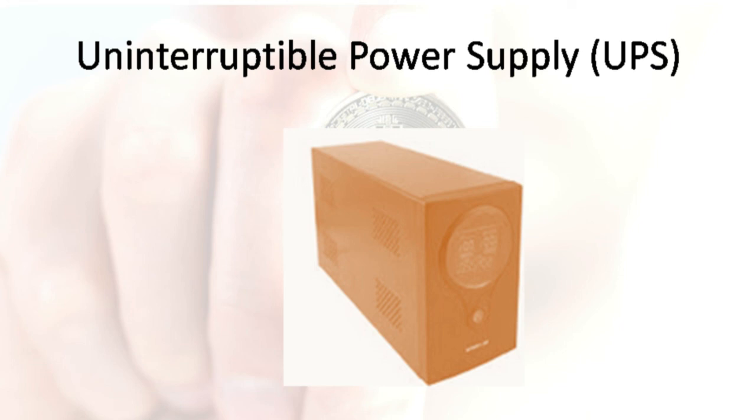So in this case, another power source that can be kicked in can be in the form of, let's say, a backup generator. One of the most important things when looking at the UPS is its hold time, and it is characterized as the amount of time from the lack of main power until the batteries are no longer able to provide the power needed to keep the load power within the specifications.